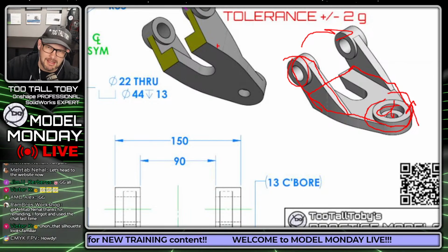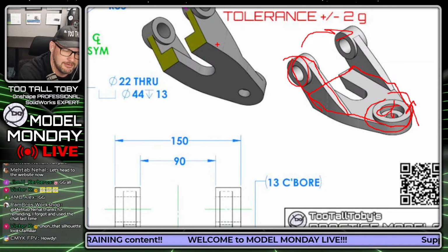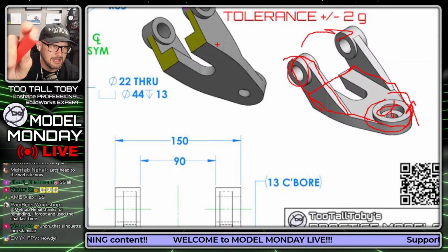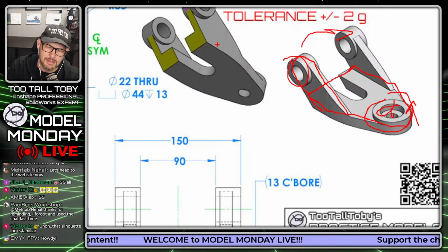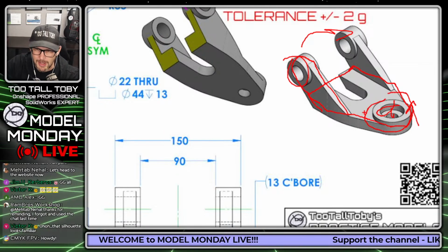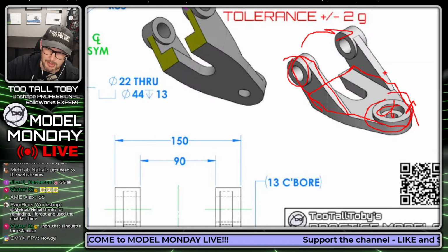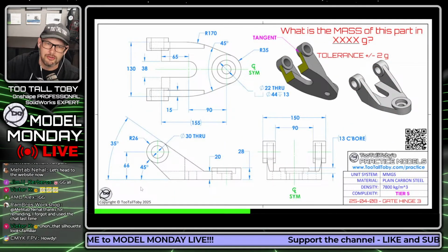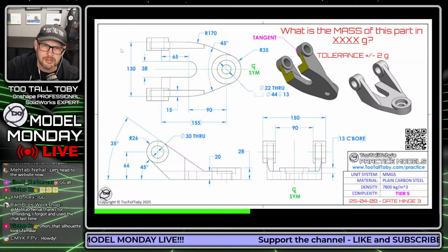So I think that's going to be the general order that I'm going to use, but this is something you always want to think to yourself. If you're looking at a physical part, if you've got something physical in your hand and you're going to model it up, look at it and ask yourself the order in which features should be built and the different types of features that you might be using to construct that model. So it looks like for this model, it's mainly just going to be extrudes, boss extrudes, cut extrudes. That should give me most of what I need for this model. So now I'm going to get a little bit more nuance with my game plan, and I'm going to ask myself, well, where should the origin be?